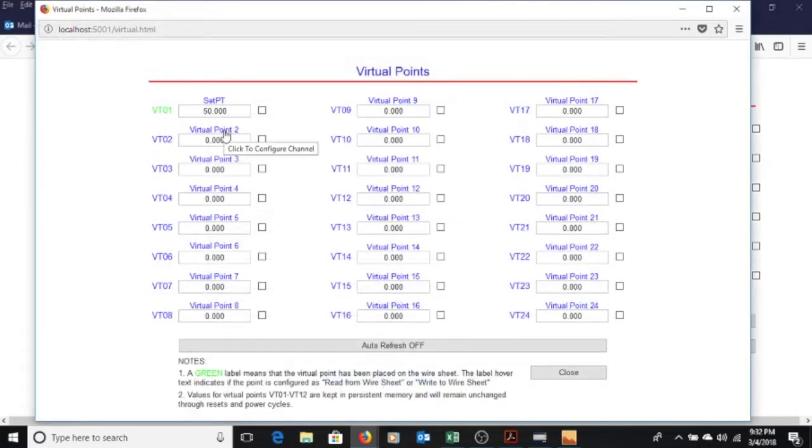If I was reading, I could see return temperature on a furnace. I could use this one as a supply temperature on a furnace. So I could be watching this in real time. Auto refresh would be on. Remember I said operating, auto refresh could be on, and you could actually sit there and watch and analyze and talk with your class about these set points and say, hey, what's actually happening in this scenario? Look at how this is heating up. Gives you a different way to learn and try to understand what's happening, with whatever system or control strategy you're running. I'm going to close this out.